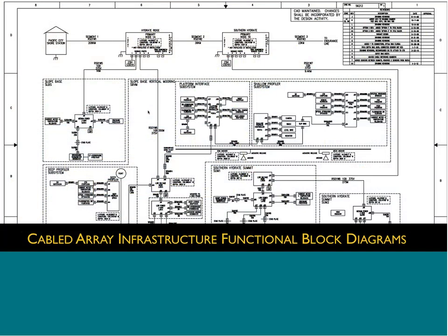This is not the greatest in terms of image clarity, but these are called functional block diagrams. They're engineering diagrams that detail from an individual connector and port on the secondary and primary infrastructure to the instruments as well as the cables, and this is part of the asset management. But they provide, I think, some very useful information to people that want to add on to the array by showing everything that's at one site, and it includes kinds of connectors as well as cable lengths.